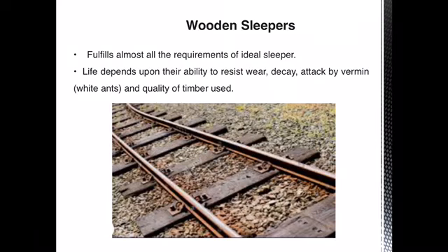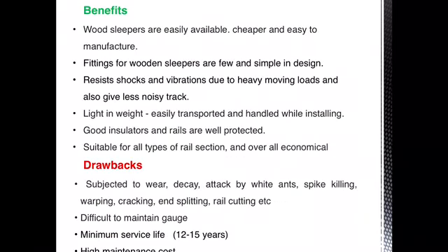When it comes to the advantages and disadvantages of wooden sleepers, we'll talk about the advantages first. Since timber is easily available in all parts of India, we can widely use this. Second, the fittings for wooden sleepers are very few, simple in design and easy to construct.